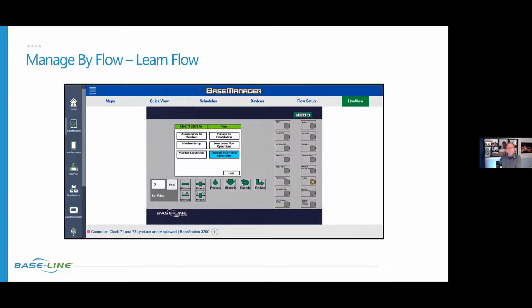I think where you're going with this is you can actually enter that flow information. When somebody calls me and they want to know how to run multiple zones at a time, this is generally how I instruct them to configure the controller without a flow sensor: simply enter the flows of each zone manually, as close as they can. Take 2 gallons a minute per sprinkler. If they think that's the right nozzle, multiply it by 10 sprinklers, enter that value.